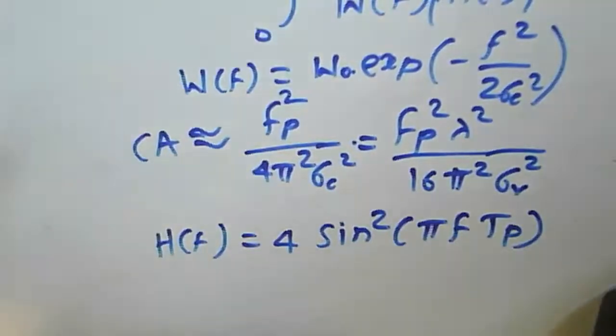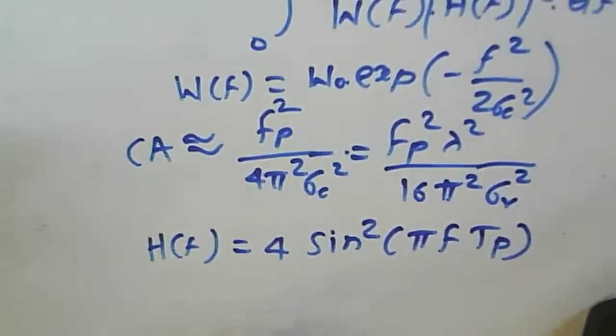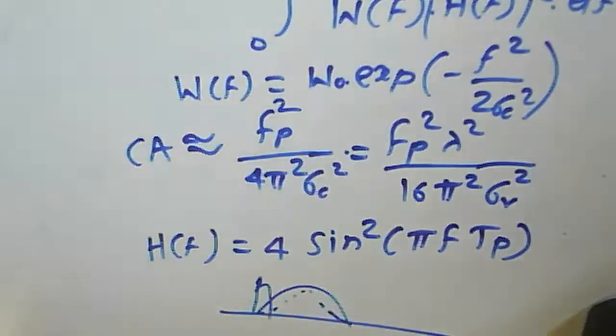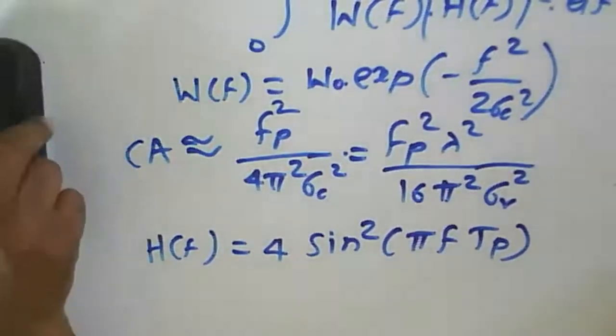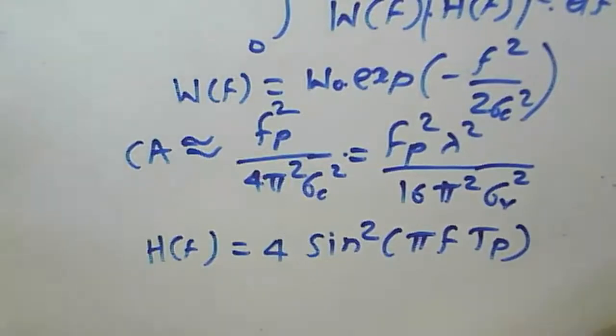Now, if you consider this 4 pi f, and the response we obtained earlier for the clutter attenuation, the dotted line we obtained, then the curve we get from this particular frequency response shows that clutter attenuation will be possible with the double delay line canceller.